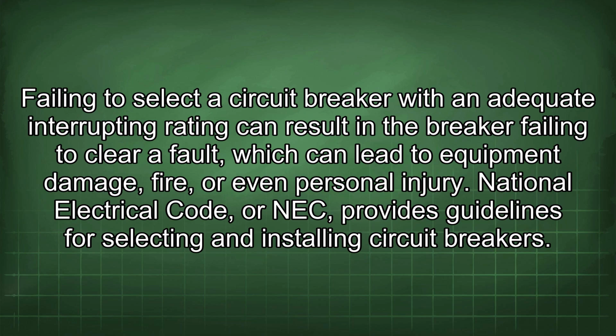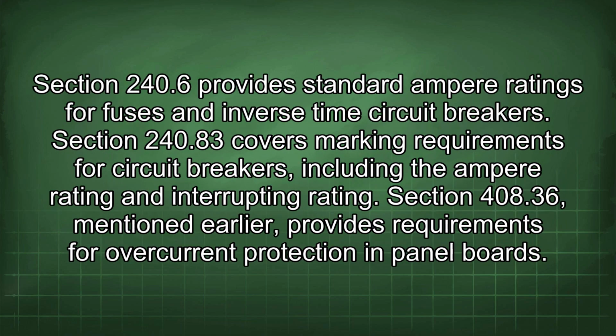The National Electrical Code, or NEC, provides guidelines for selecting and installing circuit breakers. Section 240.6 provides standard ampere ratings for fuses and inverse time circuit breakers. Section 240.83 covers marking requirements for circuit breakers, including the ampere rating and interrupting rating.